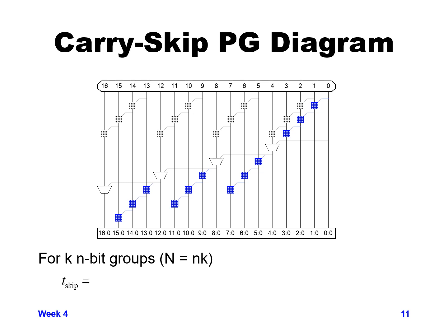Now at this point we can look at what's the longest delay from this point. We can either go through 3 blue boxes or we can go through more to the left. So the longer delay is going to be if we go from the white box and skip over to bit 8 where we're hitting another white box.